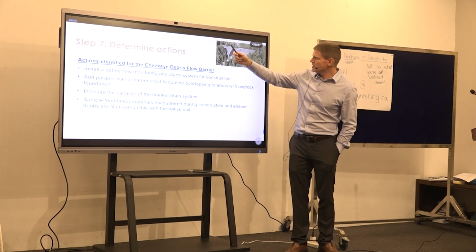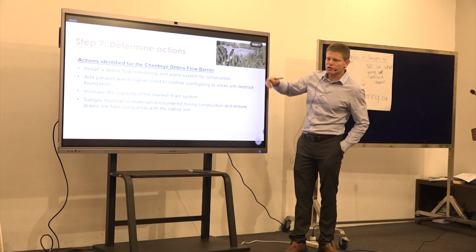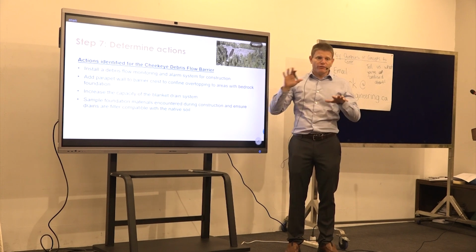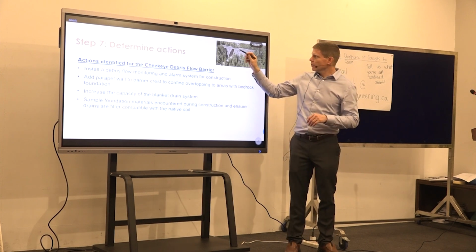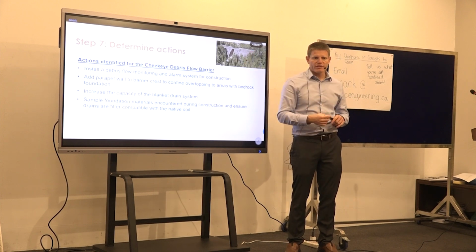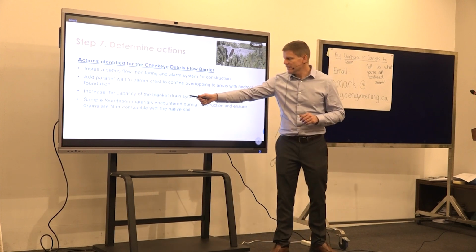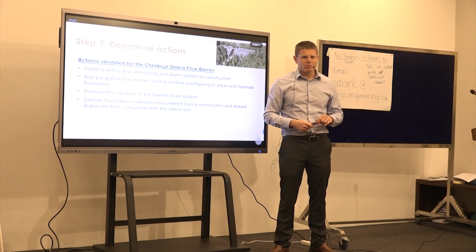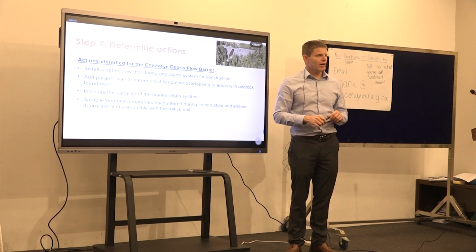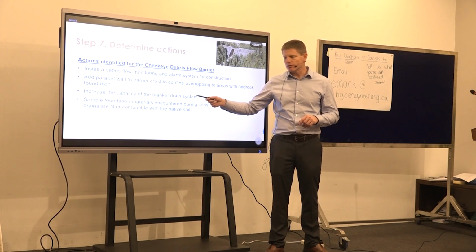Another thing that we did was we installed what we called parapet walls, these walls that were on top of the structure. We put them there because we wanted to protect the foundation from flows that overtop the structure. So we forced the flow into a spillway that spilled onto rock so that we didn't get erosion of that soil foundation. Another thing is we realized that our drain system, we talked about piping, that's what we've worked through as a group. We learned that our structure was somewhat susceptible to piping, and so we increased the size of our drain system to address that issue.